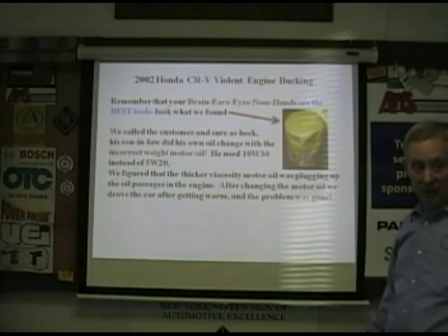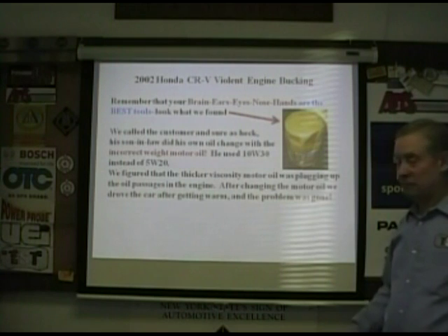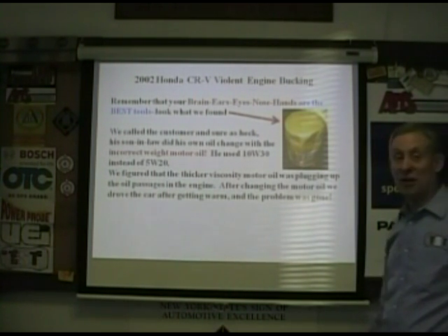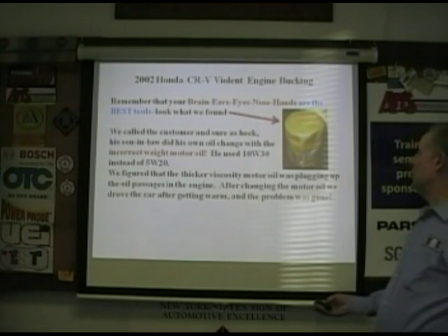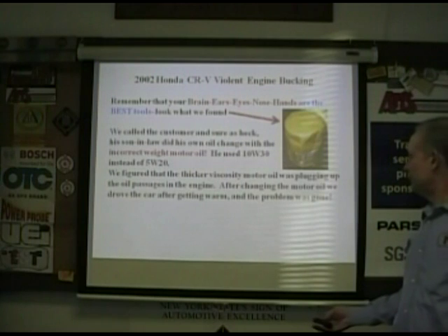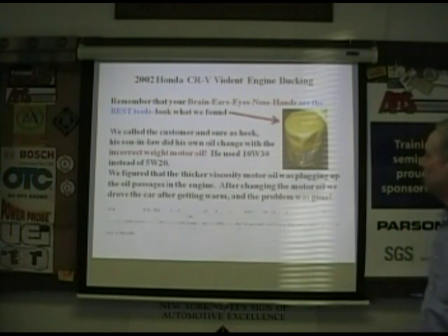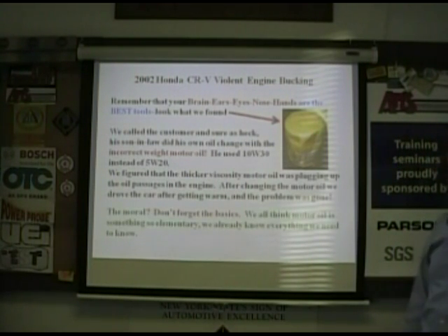Or maybe you would. But in ALLDATA, they give you that information, what times of year and what temperatures you can use. That's right. And the manufacturer's manuals also do it. Manufacturer's tech info has a lot of that too. Hondas want that 0W-20 on their hybrids and stuff like that. Moral, don't forget the basics.